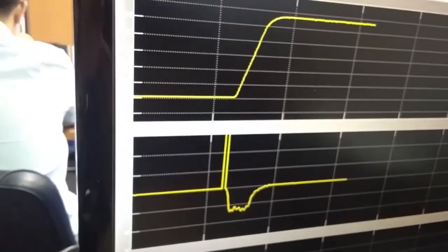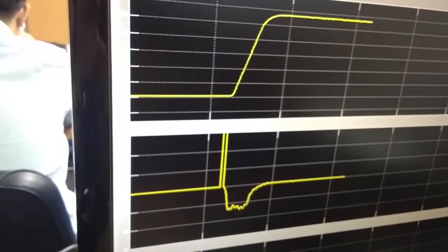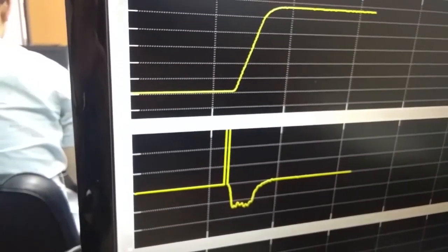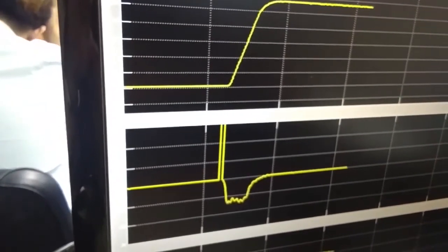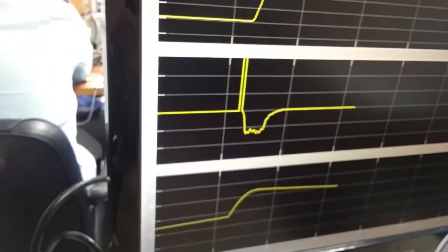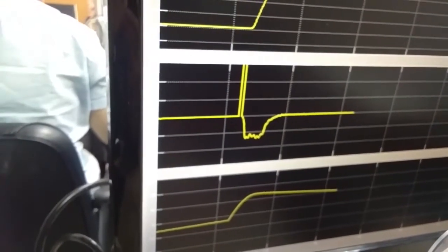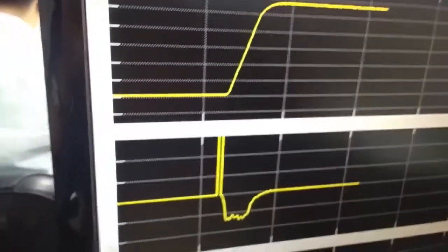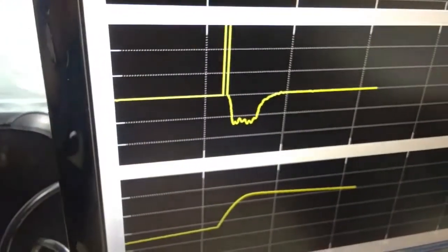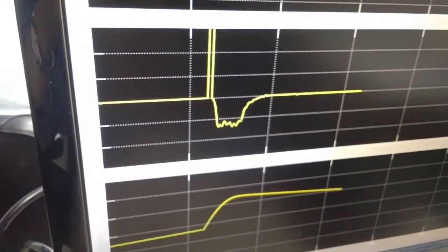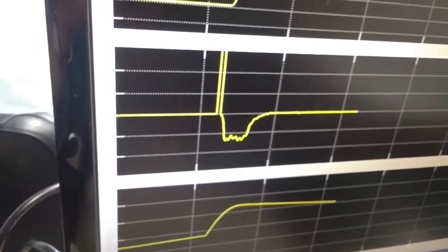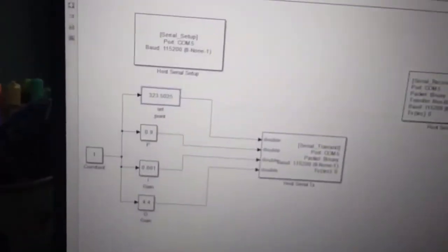When the response rises up, you can see that the D value will show a negative value because it's trying to retard the system, while I control is trying to speed up the system like P control. And because the response graph has some error, the value of I control will decrease at some point in time.